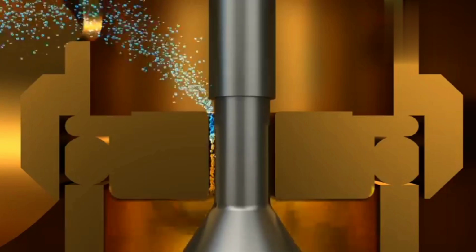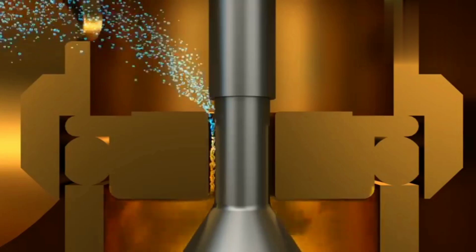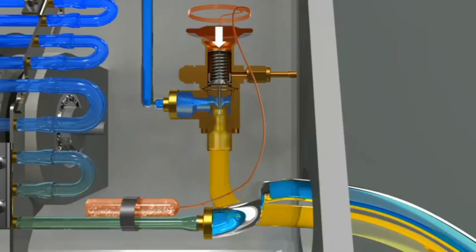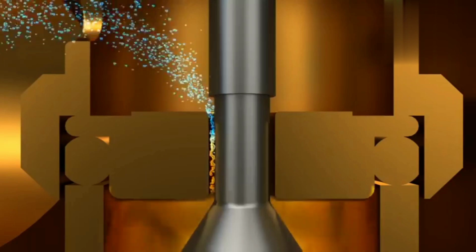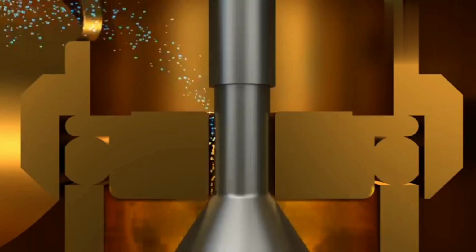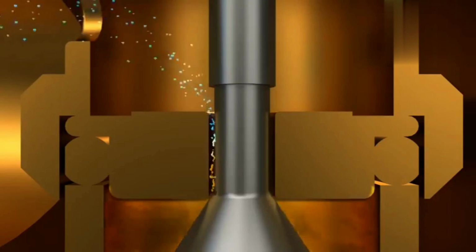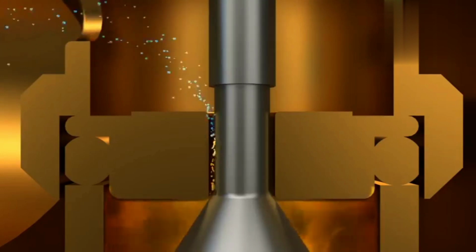When the amount of refrigerant going into the evaporator surges, cooling emission surges too. When the temperature at the exit of an evaporator drops, gas pressure drops and the amount of refrigerant going into the evaporator in turn drops too. Applying the above principle, an air conditioner controls the amount of refrigerant injected into an evaporator to prevent overcooling.